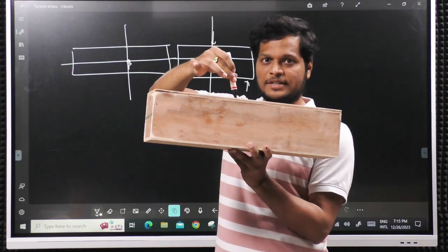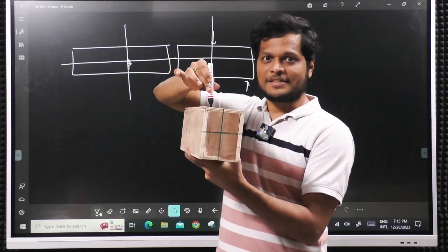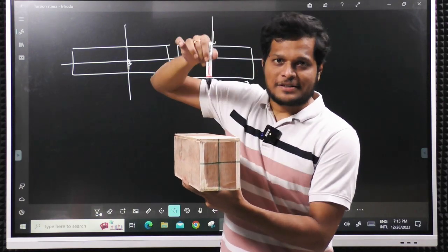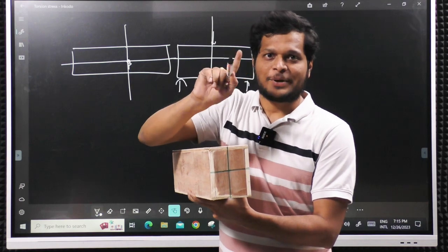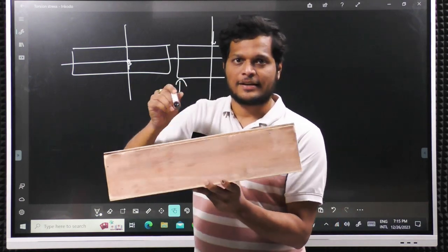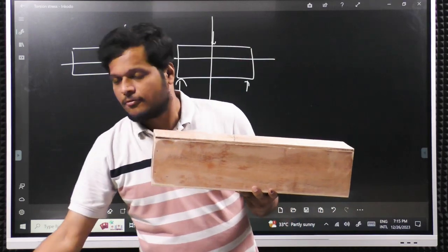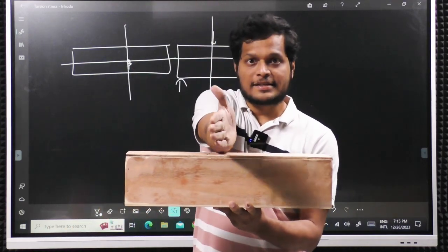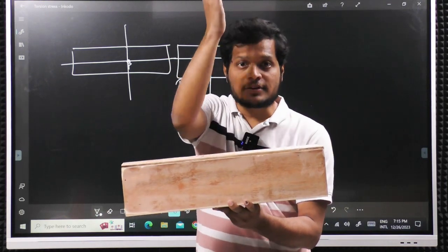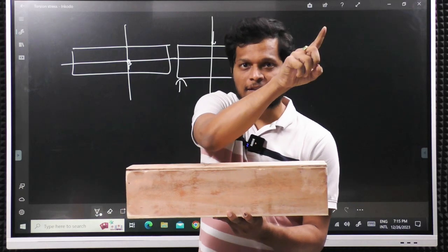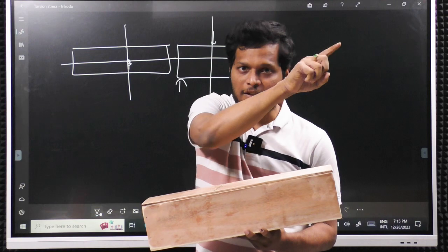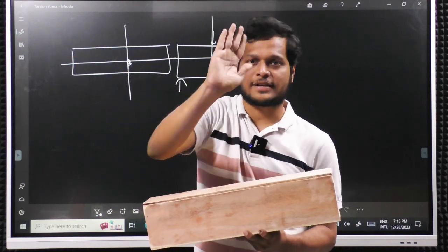Okay. Actually the beam is like this. I applied a load like this. Identify about which axis it is bending. This y axis is parallel to the load line. So it is not bending about y axis. It is bending about x axis. This. Okay. For this beam there are 3 axes, right? This is x, y, z. It is rotating about x axis. The bend whatever you have is about x axis. Okay, the rotation is about x axis.